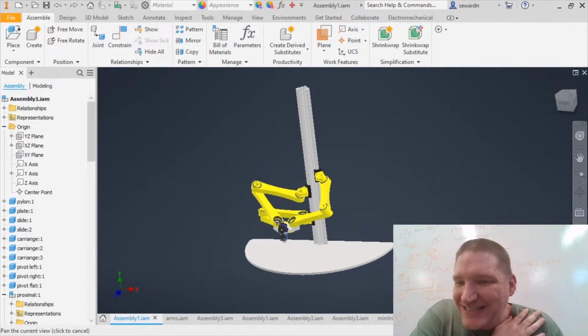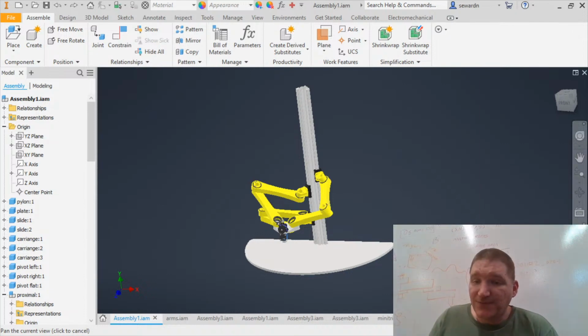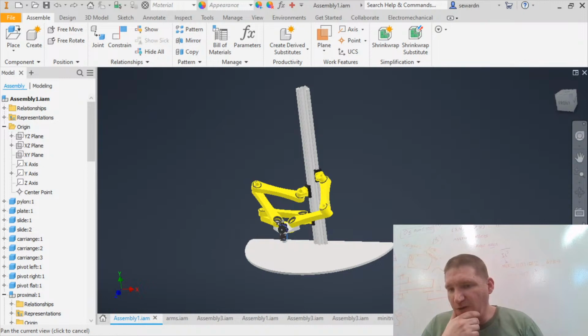Let's see, Waffle Beaumont. Instead of using a linear rail, which might bend down a little, as some people have mentioned, I think that maybe two smooth rods separated by some distance might give more rigidity. This might be a counterintuitive thing, but long round rods are very, very bendy.